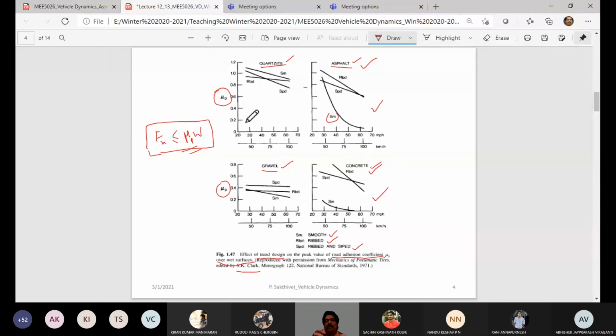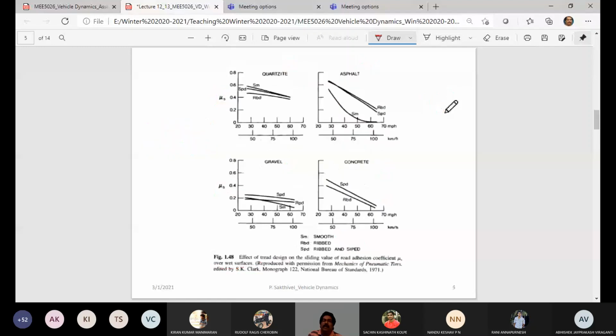Also, another important thing is the coefficient of static friction. That is the scenario of 100% spin or 100% skid that you have witnessed in our earlier study. So that's what is looked at here again. In case your slip value goes beyond the maximum slip value and it's going to be 100% spin, what would happen? Your entire interaction would be μs times W. So again the same scenario, you could see these differences here, right?